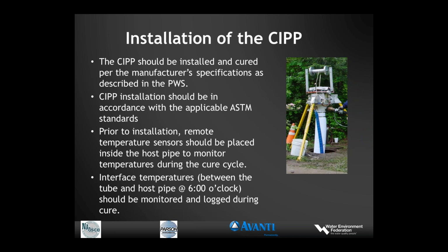Installation of CIPP, there on the right, you see an installation machine for air inverting small diameter cured-in-place pipe. But again, very important, the CIPP should be installed and cured in accordance with the manufacturer specifications as described in the performance work statement. And also should be installed in accordance with all applicable ASTM standards.